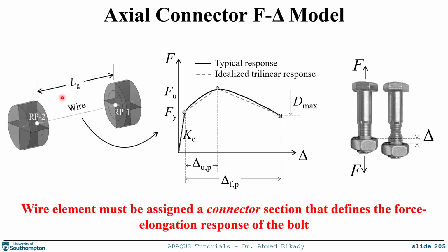In order to do that, we need to define a connector section. This connector section is equivalent to a material model when we are dealing with solid elements. But instead of defining stress strain, here we are defining directly the force elongation response of the bolt. How does a bolt response look like in tension? It looks like what we are showing over here in this slide.